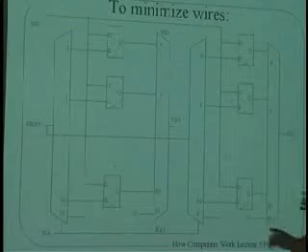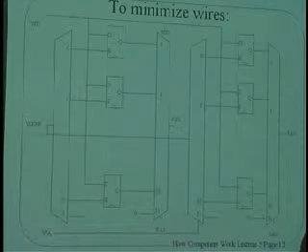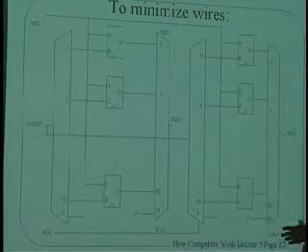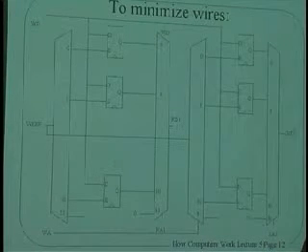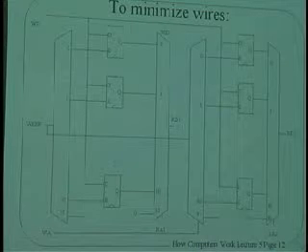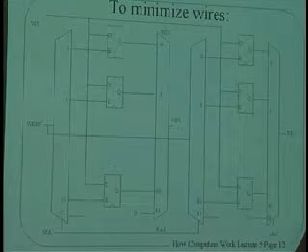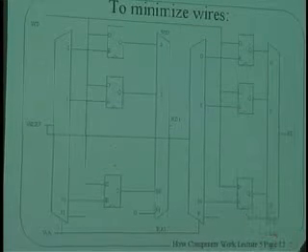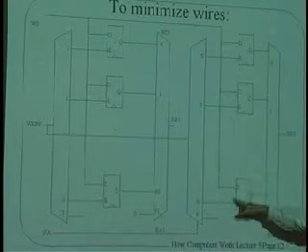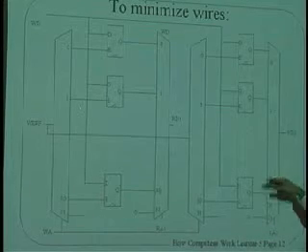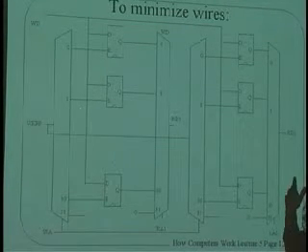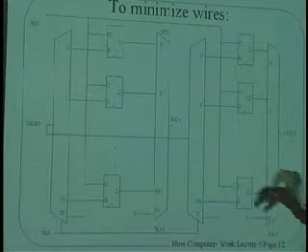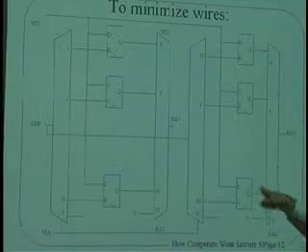So this is how to build a two-port register file out of two one-port register files. And the answer is to just sync them up so they both have the same thing on them. Okay, it's kind of a cute trick. And in particular, it turns out that the circuitry involved in building this, guess which takes more circuitry? To store the bits or to select the bits? Now, you'd obviously think, oh my God, remembering, building a memory is a hard thing, right? But actually building the selector is harder.